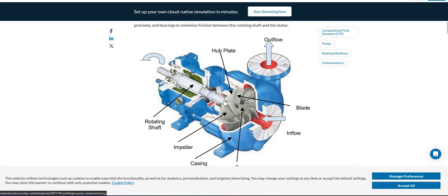The shaft is always going to be made of steel, with different geometries, different diameters, and different edges, because we are going to have seats for the bearings and seats for the other parts on it, like the rings and the gears if we need to have them, and the coupling at the end.